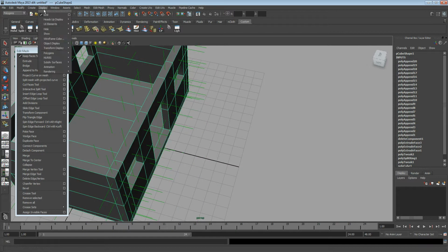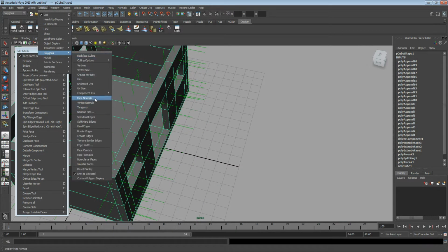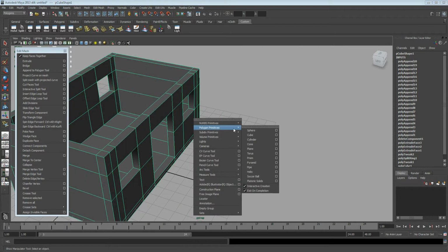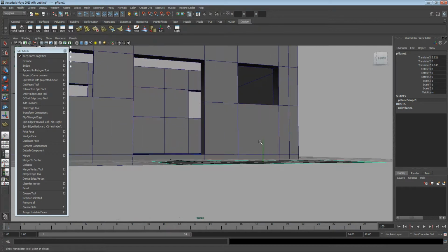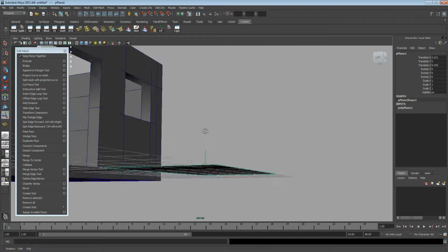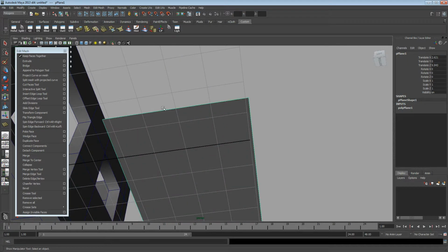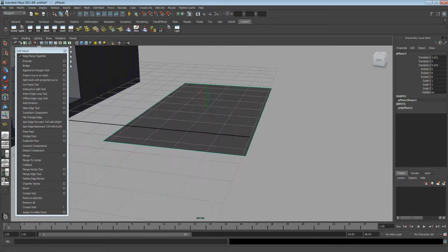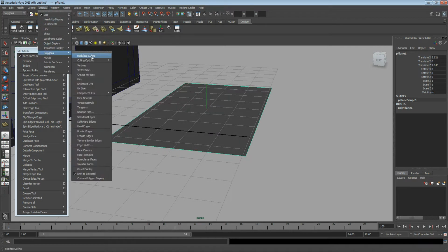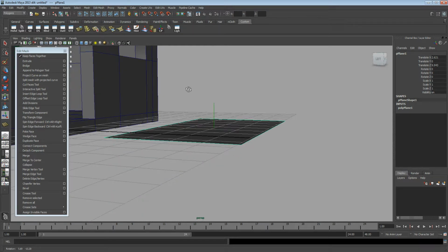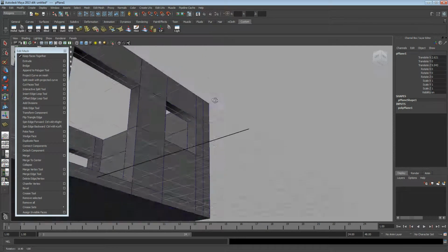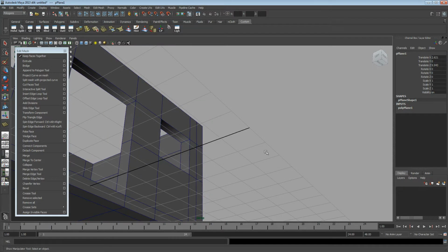So how do we really look at Backface Culling? Let me show you a quick example. Let me turn this face normal off. Let's say I create a plane, and with that selected, I'm going to turn on my face normal. Right now you're seeing this face normal and it's only pointing upwards. What happens when I move to the opposite side? With the face selected again, I go to Display, Polygons, Backface Culling. So when I'm behind the plane, it's no longer showing.